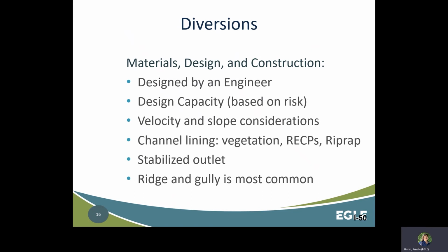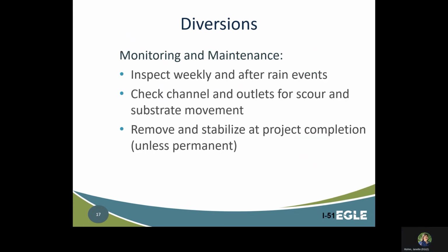Velocity of the runoff should be in the non-erosive range. A calculation must be done with the determination based on the specific soil type and vegetation. Increased velocity can be accommodated with the addition of rolled erosion control products in addition to vegetation.